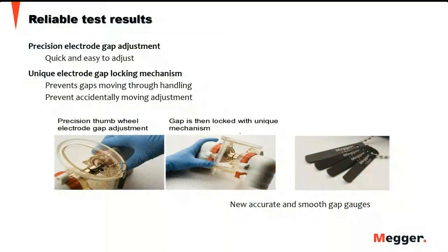And we also have the spacer. As you can see, this is the spacer here. It has a black anodized coating. So when you start to see some silver color here, that means the accuracy of that gap is no longer correct.